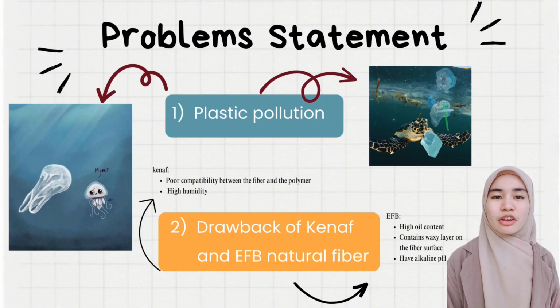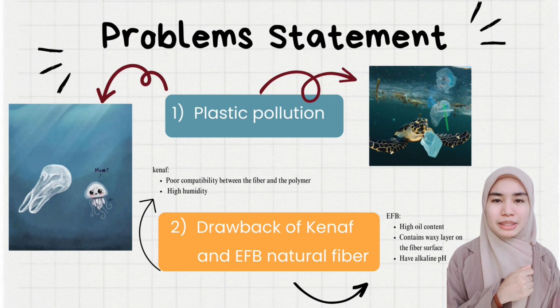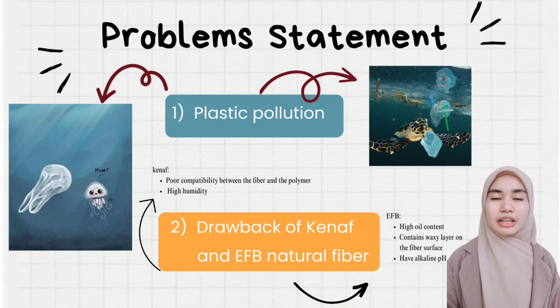Problem statement consists of two problems. First, plastic pollution, and second, drawbacks of Kenaf and EFB natural fiber. Kenaf has poor compatibility between the fiber and the polymer and high humidity, while EFB has high oil content and contains a waxy layer on the fiber surface.